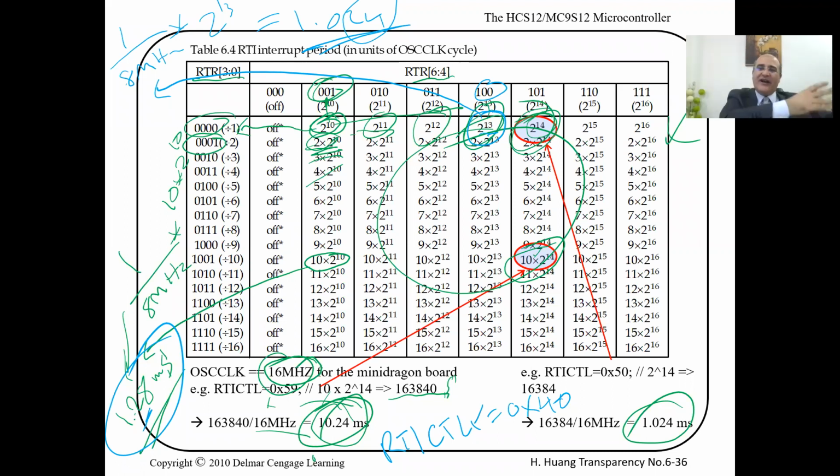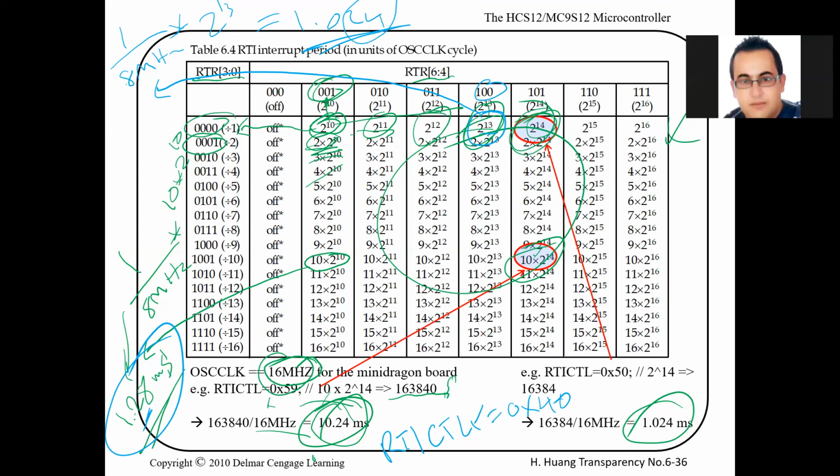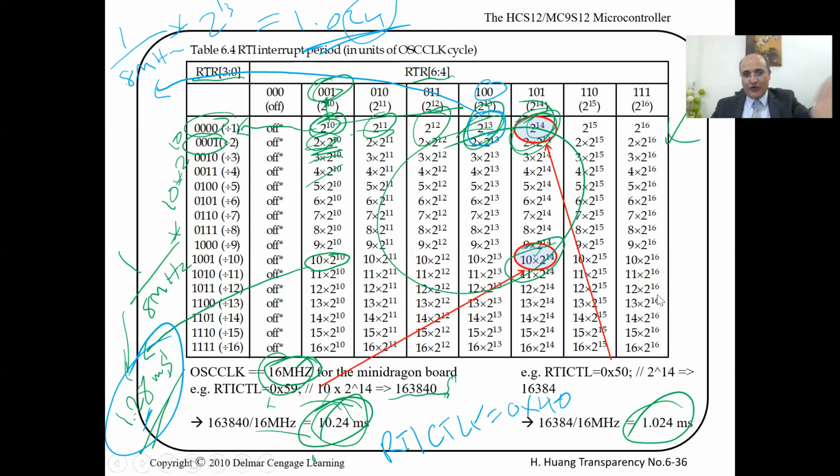It can increment i, and when i becomes 500, then this is 500 milliseconds, right? Got my point? I'm going to do the other part by software. If you want it totally by hardware and you know the fixed time, you can just go and make it larger, with all these values. But my intention was to build together with you this delay function that is based on hardware.